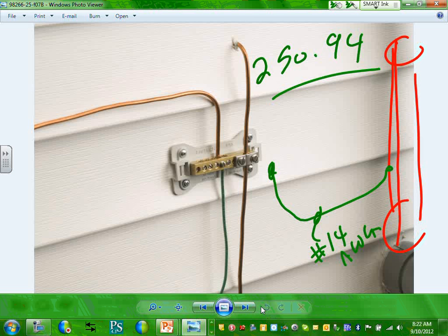So you bring it right in here, so you bond all your systems. If my coaxial cable is coming in here, one more time, you take the shield of it, and there's a slot right here, and you ground your system directly to it.